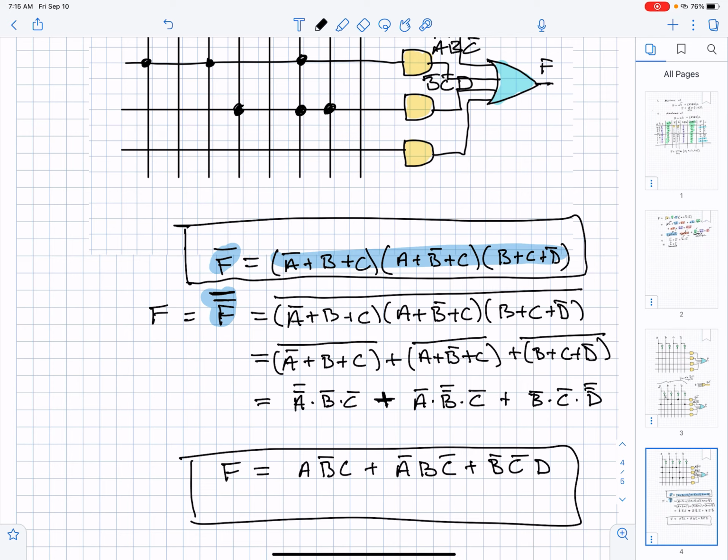So now I take the whole logic expression and I put the complement sign over everything. From there, I'm doing De Morgan's theorem on each piece. The De Morgan's theorem would be I break the line, break up the complements, and all the and symbols in between.